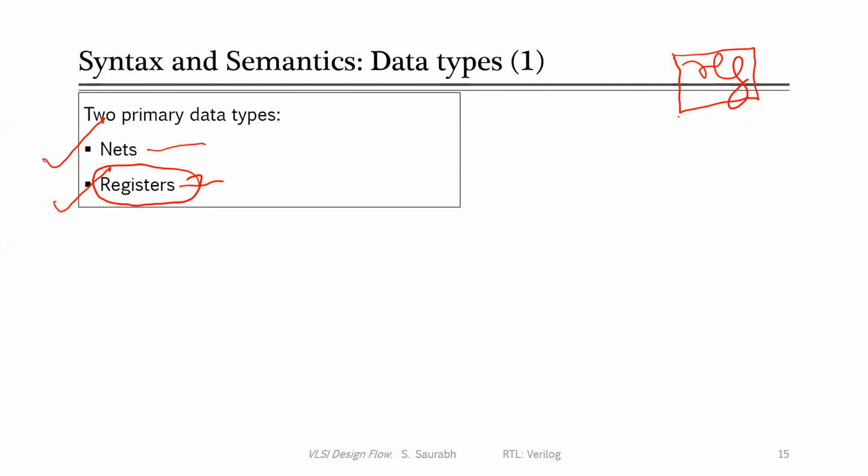See, in behavioral models, we also use nets, right? It is not that we always have to use registers. What you want to say is that in a procedural block, you always need to write to a register, right? Yes. You are somewhat correct, but the main thing is that these registers holding value is for the simulators and to specify a kind of behavior. It is not that a register will lead to a memory element, okay?